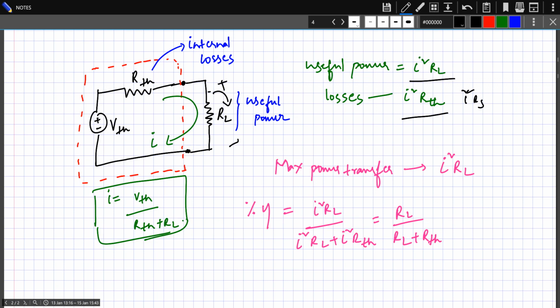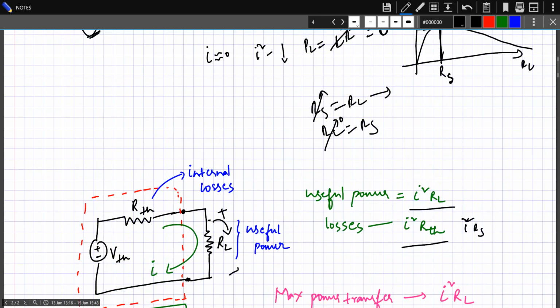Mind you, we are not talking about the power that is being consumed; the power analysis is done by the maximum power transfer theorem. So if we want the maximum power to be given to the load, we have to keep the load resistance equal to the source resistance, which will give us the maximum absolute value, suppose 20 watts, 30 watts, like this.